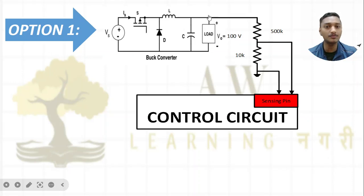So maximum current will flow through this particular branch, and very less current will go through this. But as both are in parallel, the overall voltage drop across both branches will be 100 volt. I will choose these two resistances in such a way that the drop across this particular resistance is less than 3.3 volt. So if this drop is less than 3.3 volt, shall I give it to my sensing unit? This thought should come to your mind. So I will just use the voltage divider and give it to the sensing pin, then I can do the computation task inside the control unit and generate the PWM.